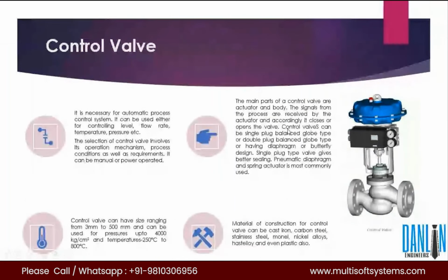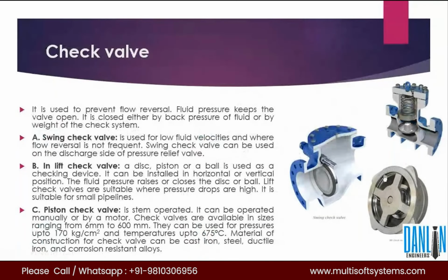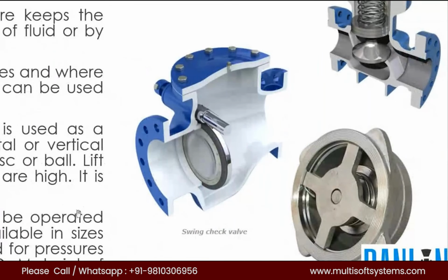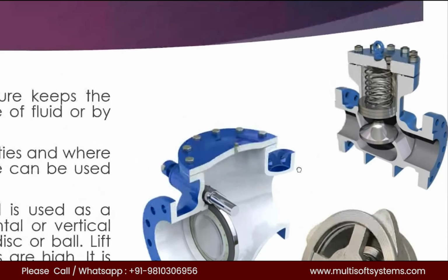And the check valve, just a presentation. Here, see, the check valve is a non-return valve. If the flow is coming like this, the disc will swing upward so the flow will go. And if the flow tries to return, it will not return back because it will stop the backward flow. So like that only, most probably we have it.